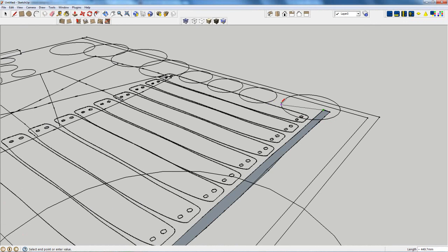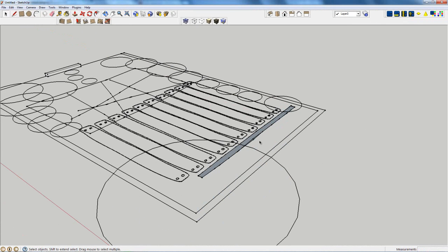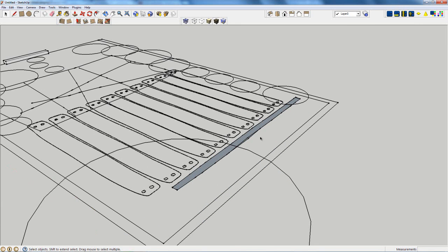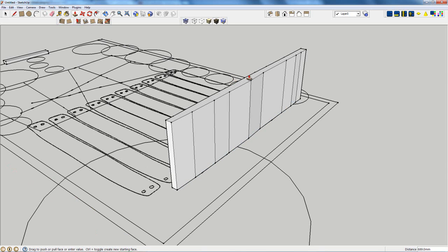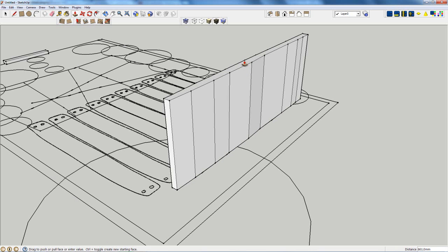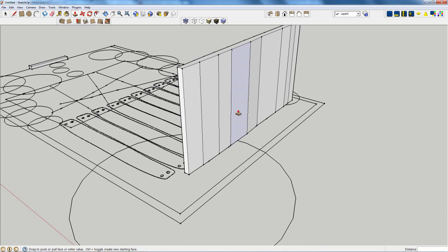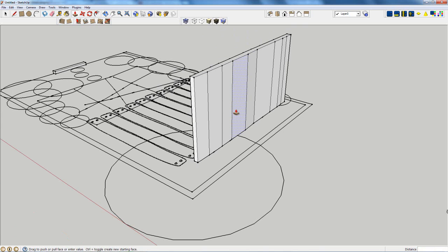So as we do that and pick our object selection tool again, we've now got our backing screen with its flexible sort of surface. So we can use the push-pull tool to select it and pull it up. And see it's got some striations on it, which we can remove later if we need to. They correspond to the sample points that we had in the original drawing. I've quite forgotten how tall we made that. I think it was 1200 mil. But remember, we're going to have to shift that whole structure up. So I'd be turning that into the equivalent of a block, which is a component.